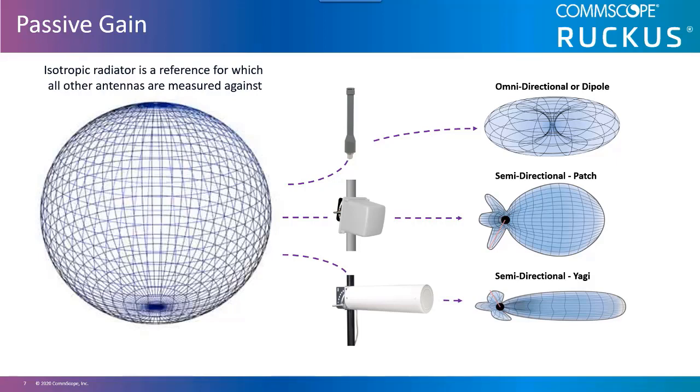For every 3 dB gain, an antenna provides not only double the signal strength, but the coverage provided will also be doubled as well. Replacing a 3 dBi gain antenna with a 6 dBi gain antenna doubles the size of the coverage area. Different antenna types produce different coverage patterns.